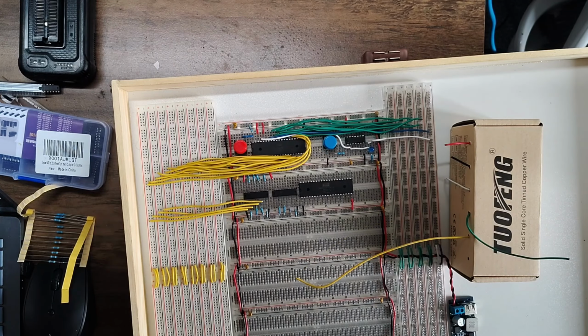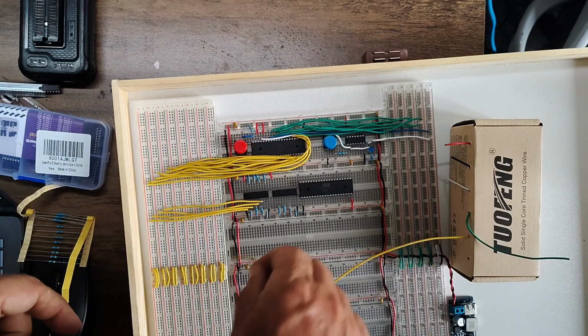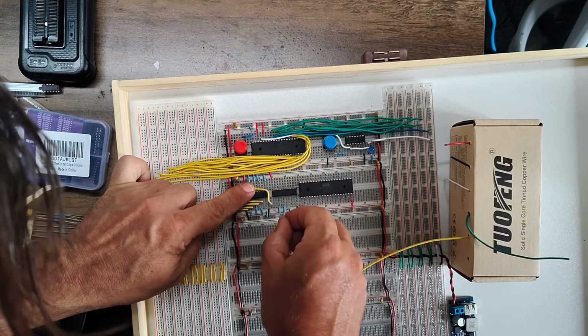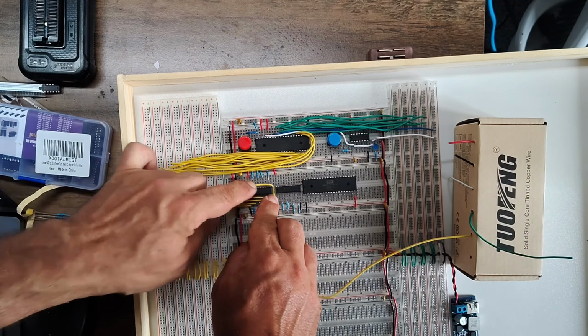And there we are. We have got the next 8 comparators all set to 0. Just before I put in the data lines, however, I'm going to need to connect the output of the first chip to the output enable of the second chip.